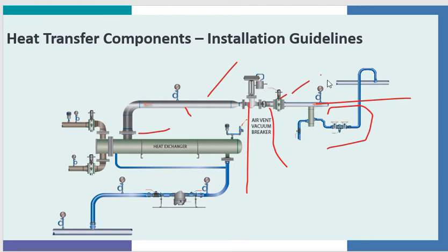The other key factor, pressure gauges. Before and after the control valve. So I know what the steam pressure is coming to the control valve, and I also know what the pressure drops are through the isolation valve, strainer, and the control valve going to my process.